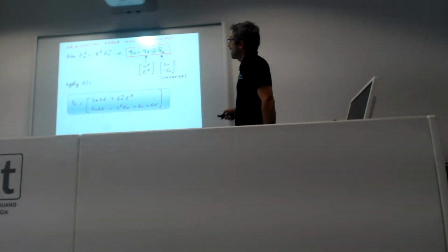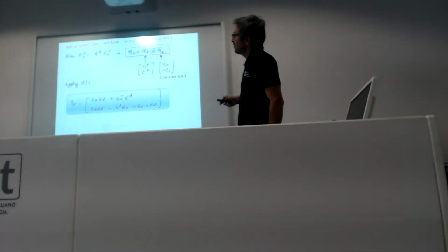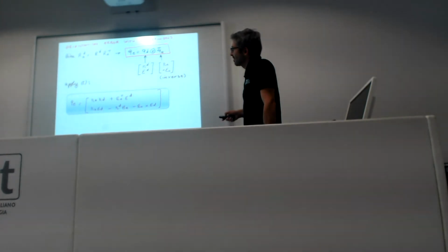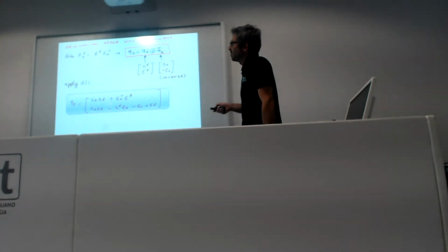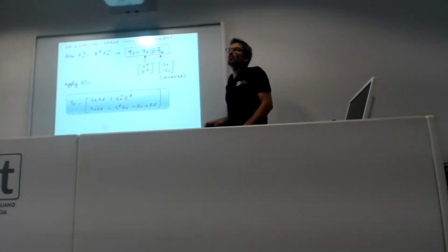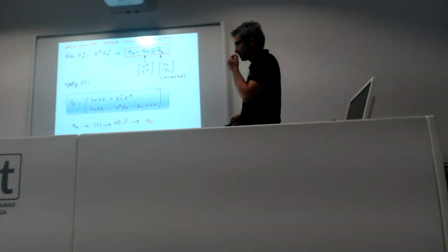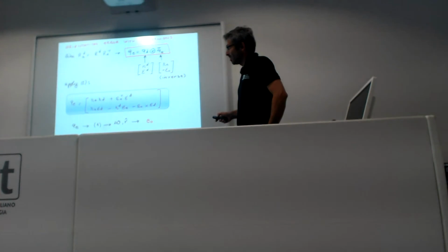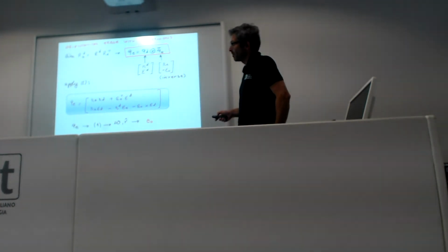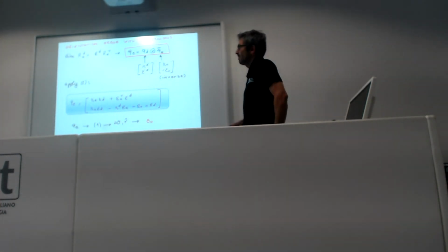Then if you apply the multiplication operator to this, we get this expression. That is what people usually use to do orientation control, because from the error quaternion you can get the orientation error with the angle axis mapping, and from there you can get the virtual moment for the controller.